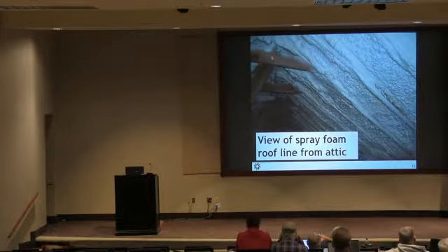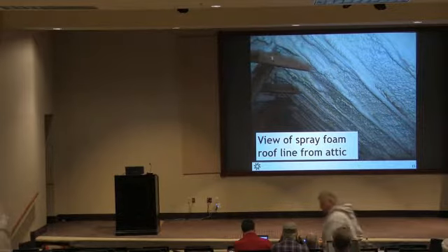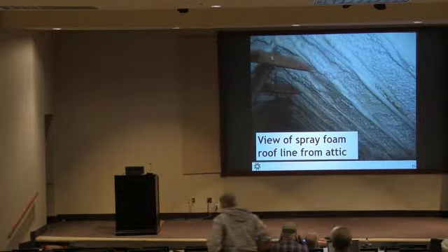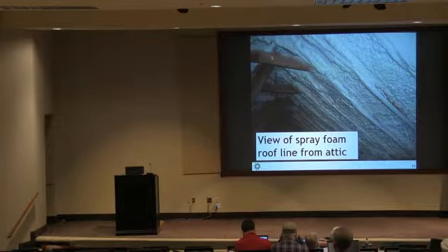That's about as big as the delta T you're going to see on the coldest winter days in a lot of homes. So, 20 to 70. And you're going to see that for months and months and months out of the year in our climate zone. So there are a lot of advantages to going this route. Again, simplification, easier to know your air barrier and your insulation in one product, done in one pass by one contractor.